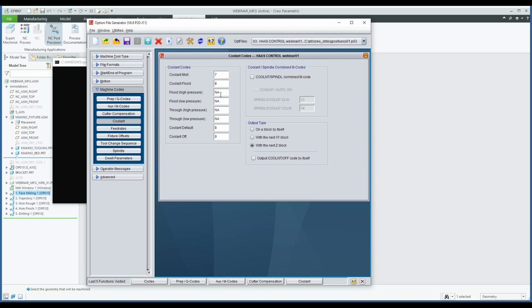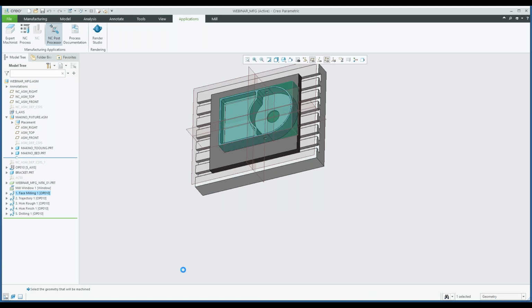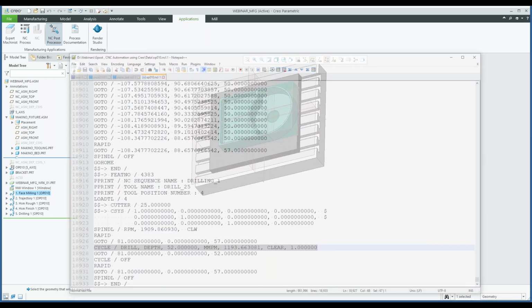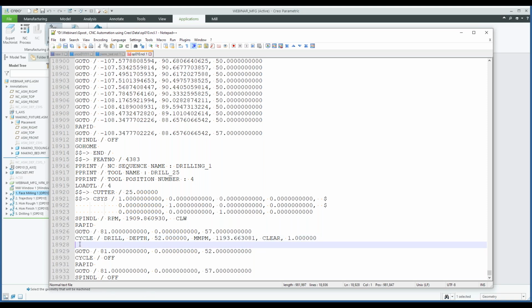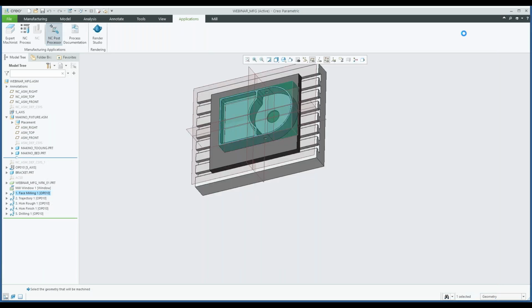And then you also need to link that up with the settings within Creo. So very important, depending on what you select, or you see now I've started it outside of or inside of Creo, now I can't go in there. So if you have any coolant in here, you must probably have a line in here that's going to tell the post processor what G code to output depending on what you've selected. So you need to tie that up with the G post.